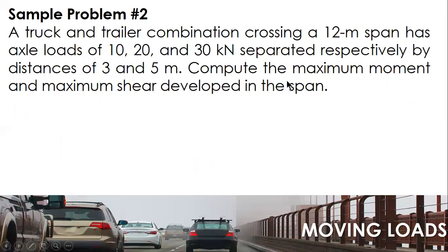Second problem, a truck and trailer combination crossing a 12-meter span has axle loads of 10, 20, and 30 kilonewtons, separated respectively by distances of 3 and 5 meters. Compute the maximum moment and maximum shear developed in the span.